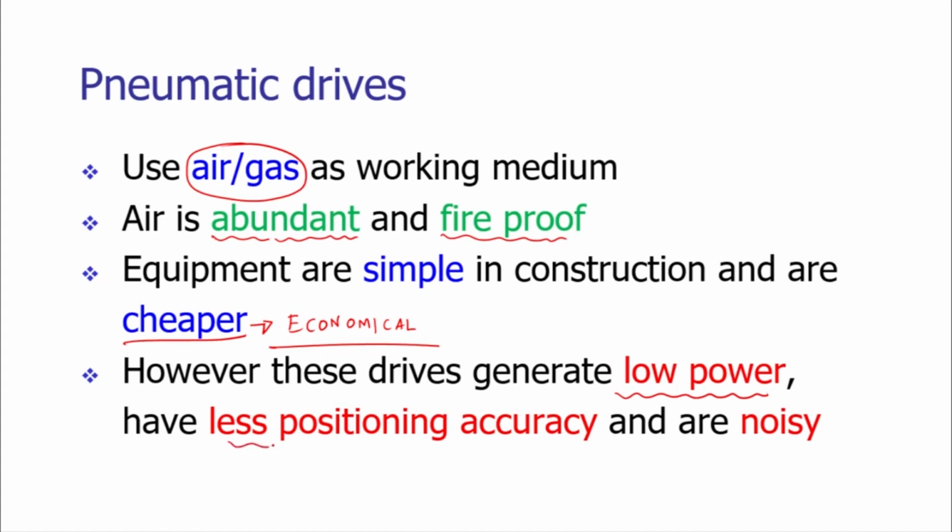The pneumatic drives have comparatively lower positioning accuracy and they are noisy, since they involve compressor-like equipment. They produce vibrations and they are noisy. But nowadays we have very good quality compressors which produce less noise. But in comparison with electric motors, the pneumatic drive creates certain noise.